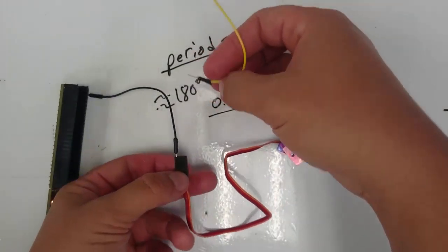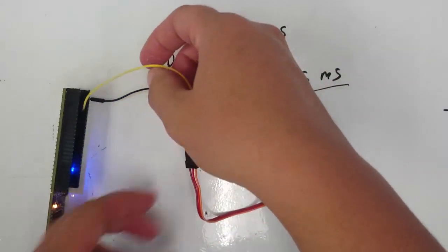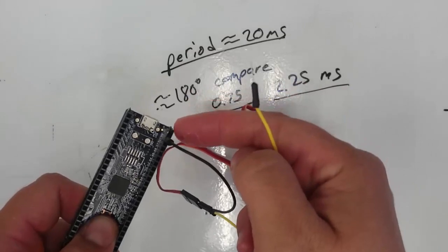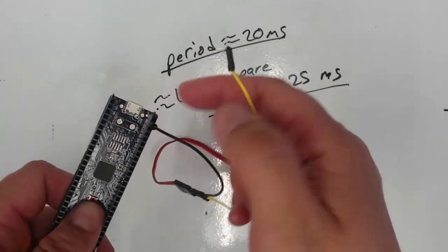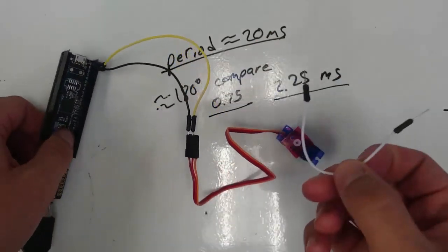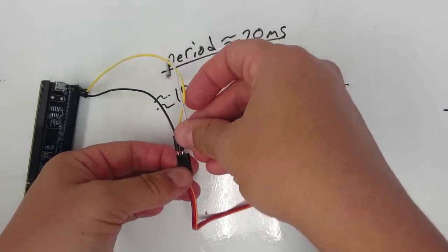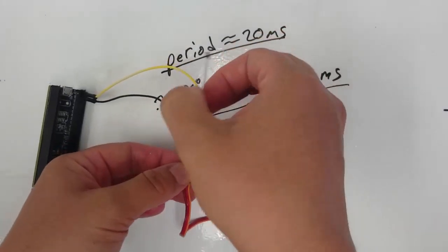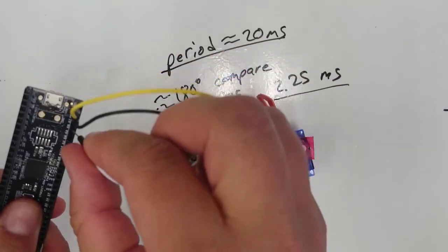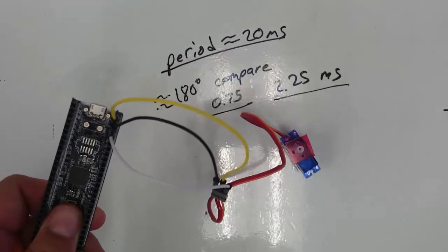Then I'm going to connect a jumper wire to the red wire. This is for power, and power from your PSoC is provided on a pin called VDD. There's one down here. Then the signal, your PWM signal, goes to the orange wire, and I'm going to connect that to pin 07 just because it's close to the other ones.